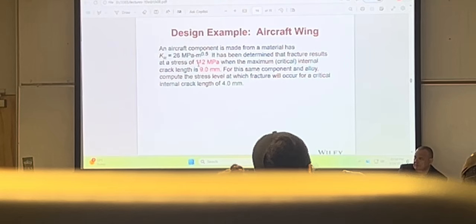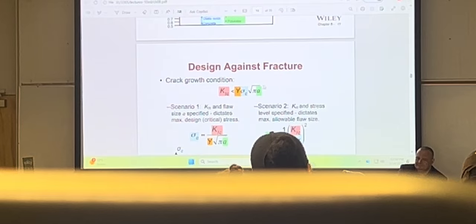Higher or lower? Think. You reduce the flaw size. So what would happen to the stress? Crack, stress. This is a constant value. We reduce this, and what's going to happen to the stress? How would it go down if we reduce this? The product of this and this. The stress would go up. The stress that the part can support would go up.